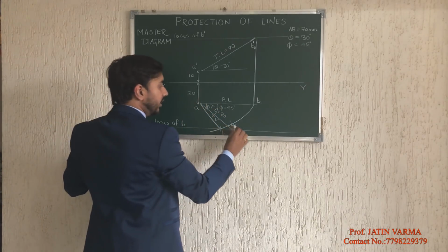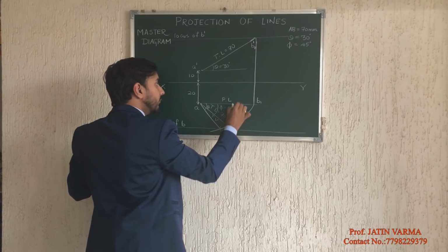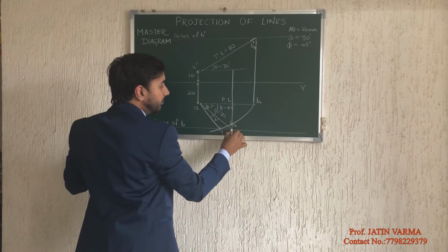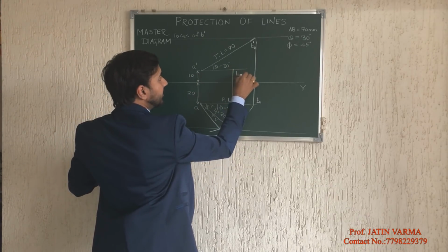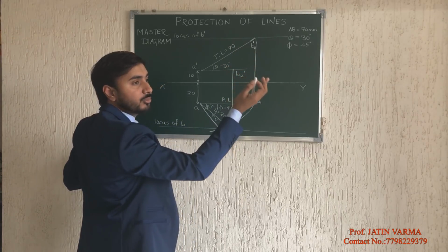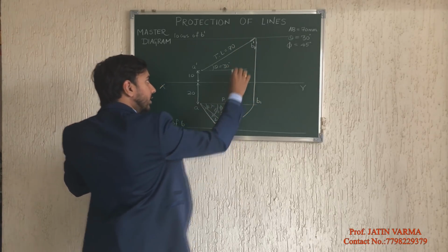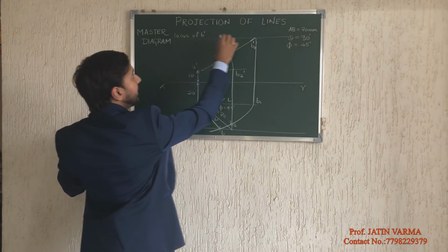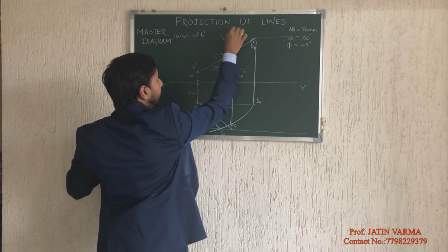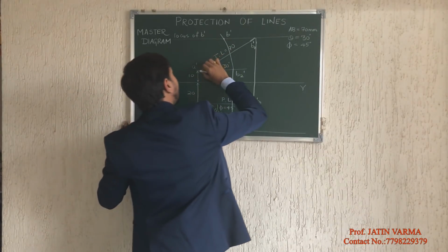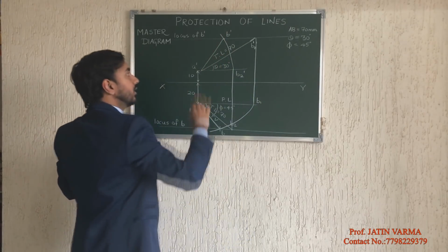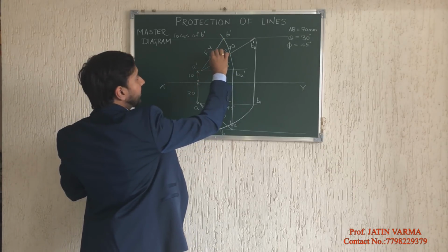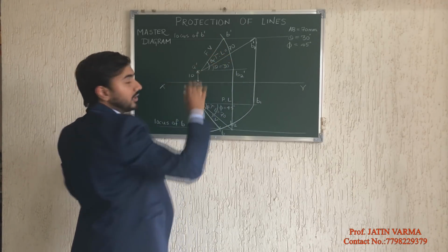Similarly, I will be projecting this B2 upwards till in front of A dash. So this was B2, and this will become B2 dash, because now I am talking in terms of front view. Now you can rotate this and make it cut the locus of B dash. So this point will be B dash. Now when you join this point, this becomes your front view, and the associated angle becomes alpha.